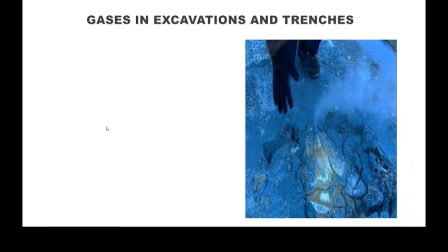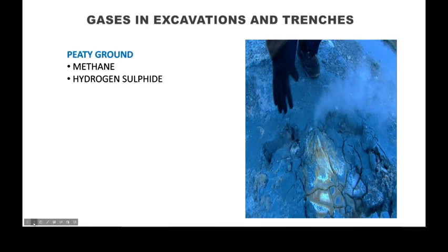Other issues that you can find doing drainage work is actually ground gases. So it's an even less obvious one than the trench collapsing on you. But there's actually a range of gases produced naturally from decomposing soils and things like that in certain areas where they may be an issue. They may be flammable, like these gases. Hydrogen sulfide is also poisonous. And even a non-poisonous gas, if it's displaced the oxygen, because it's denser than air, then that can cause you to suffocate as well.